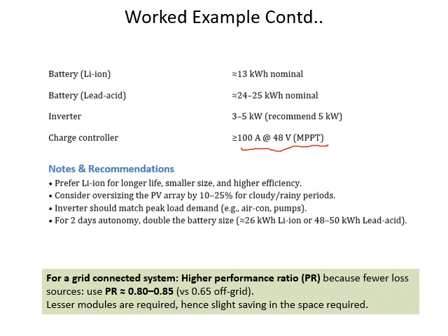For 2 days autonomy, double the battery size. If you want to run for 2 days continuous, then depending on the battery, you have to double the battery size depending on the battery type.